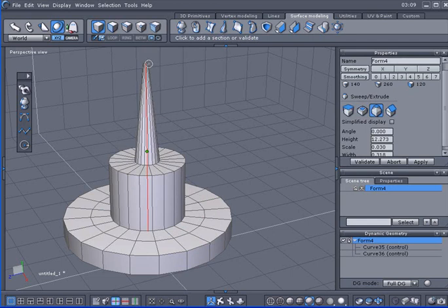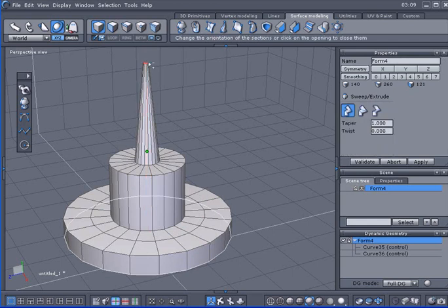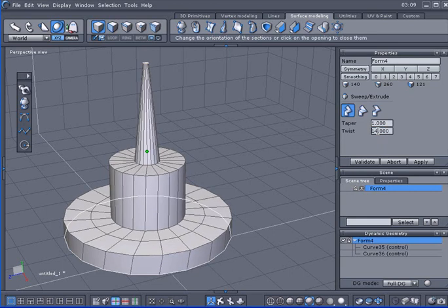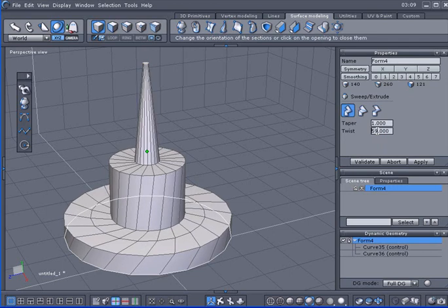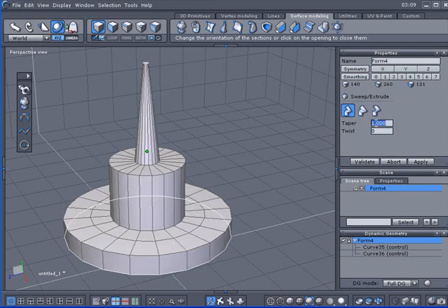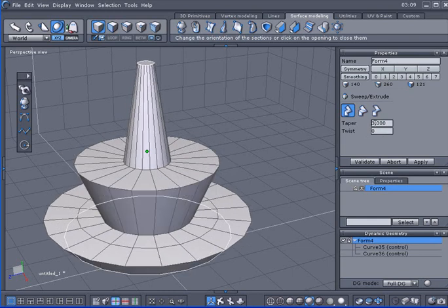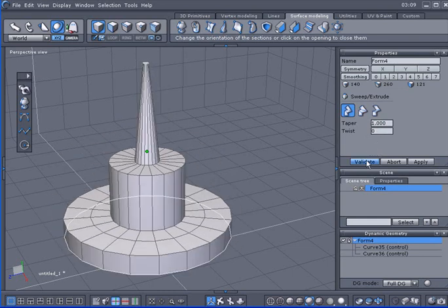and I'll just kind of bevel it out like this. I'll double click at the end. Double click, don't validate on this one here. Move my cursor in here, use my scroll wheel and my mouse, which will twist it. As you can see it twisting. You got other options up here, the taper, type the value in, set it back. Just all kinds of good things you can do with it.